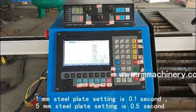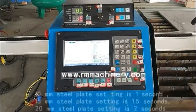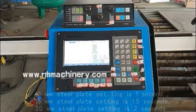1 mm steel plate setting is 0.1 second, 5 mm steel plate setting is 0.5 second. 10 mm steel plate setting is 1 second, 15 mm steel plate setting is 1.5 seconds.